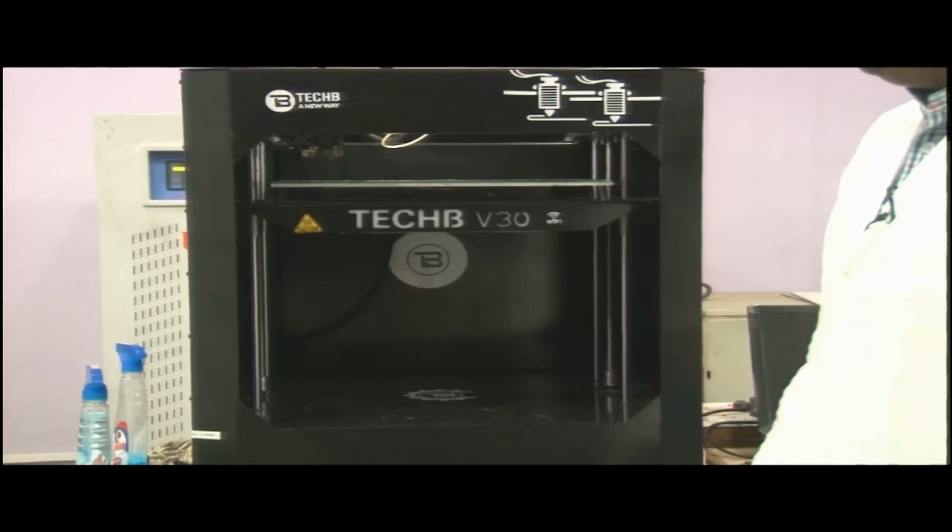When we heat ABS, the smell is quite annoying. In PLA this is not the case. So this means that printing using these parts is more friendly for the operator, and PLA also seems like a better overall choice because it features a far lower melting point as well. The melting point of PLA is quite lower than ABS. So I wouldn't move into that track now.